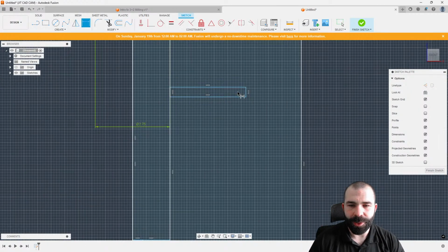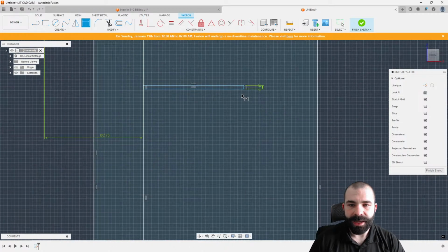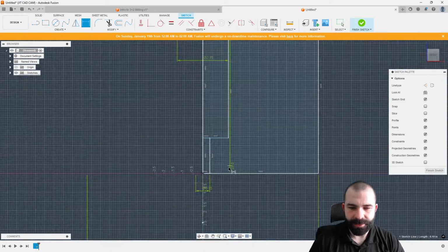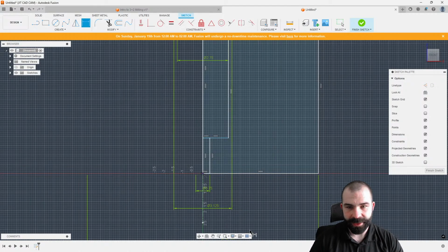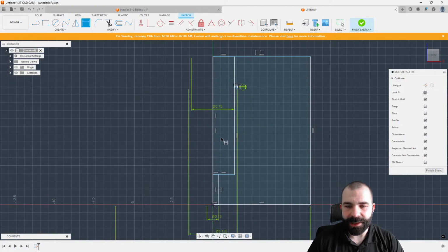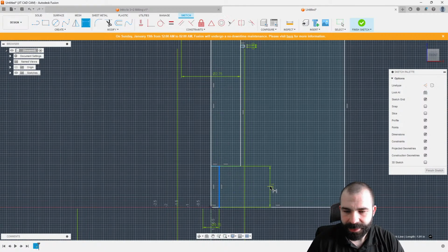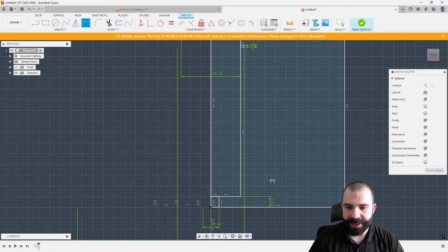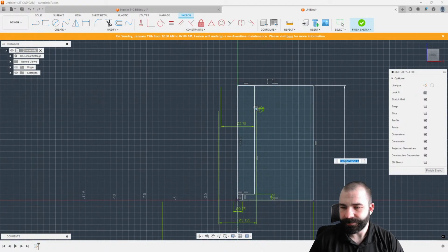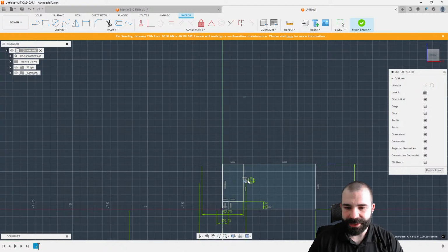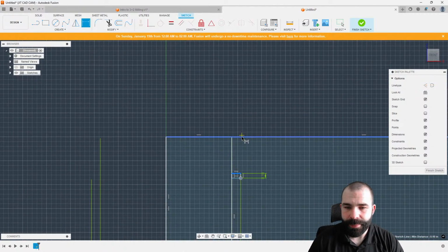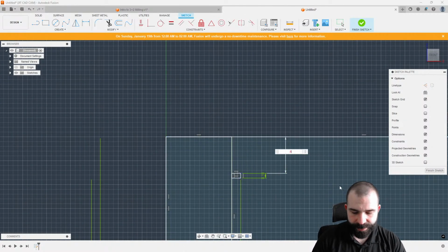And then our O-ring is probably going to be something like 1.00, and that diameter of the O-ring, plug that in. We went, what, 2.75? Let's go 1.25. Almost looks like a part, right, guys? Height, 0.5. Overall height, go ahead and go with like 3. Of course, we need to place our O-ring groove. Go ahead and put this 0.5 from the top, right?